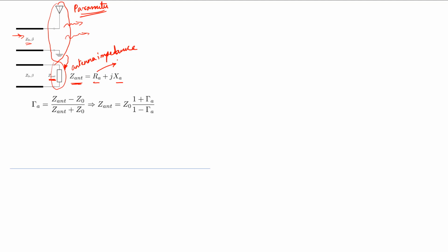Then the resistance is going to be a high value, and what this resistance really signifies is the radiation mechanism that is captured as loss. The radiation is captured as loss by this resistance. We know when there's a resistance, there's I squared R ohmic loss. That kind of loss is being captured as the equivalent radiation that the antenna does.